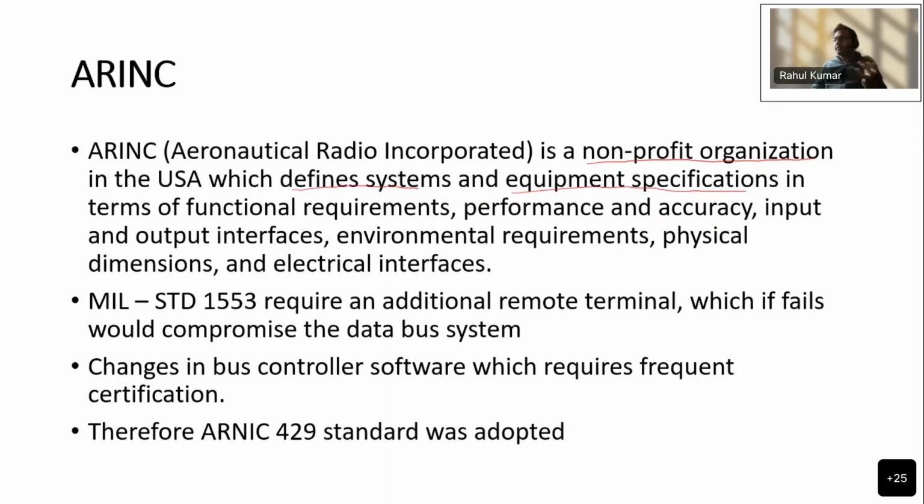Now military standard 1553 had some limitations. Okay, so I've mentioned them here. So for example, for a military standard 1553 bus system, you need a remote terminal. Okay, so every subsystem was connected to a remote terminal, which was then connected to the bus.